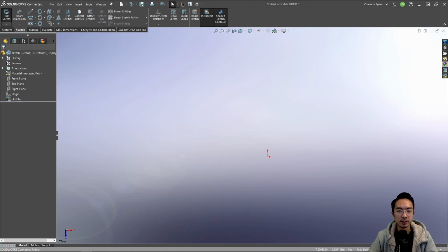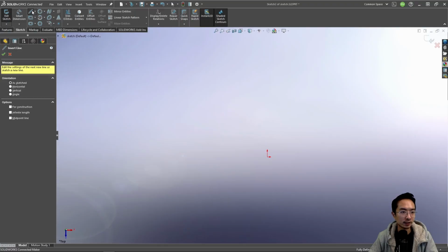Okay, in this video, I'm going to talk about sketch relations in SolidWorks. Last time we talked about smart dimension, which is a way to dimension the length or location or angle of different features inside your sketch. Sketch relations are another way that can help you define. When I hover my little pencil tool, you can see a vertical and horizontal symbol pops up. Usually anything in those little squares is the type of relation that it's suggesting. And this is the coincident relation here, this yellow one.